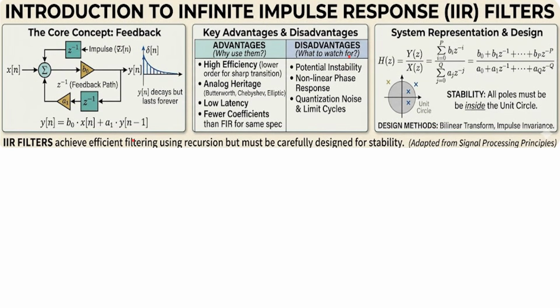So question number one is, what is this IIR? IIR is the infinite impulse response filter, right? So here we will have an infinite number of impulse responses. And what is this impulse response? Here you can see, for this one filter, how many impulse responses are there? Multiple. The amplitude may be very small as we move along in time, but the number is almost infinite. That is why this is called the infinite impulse response.